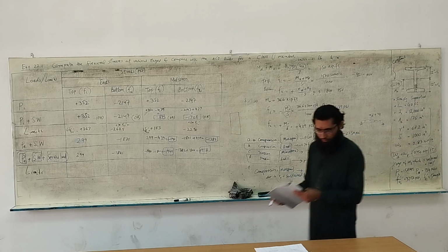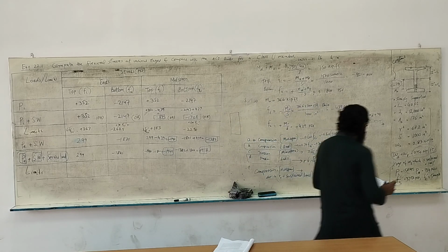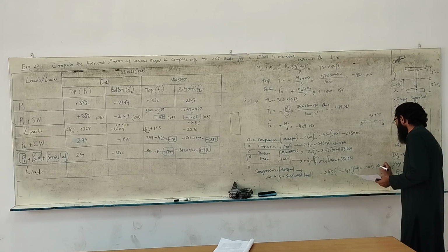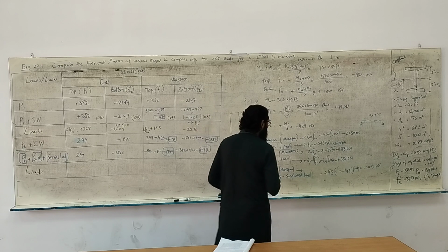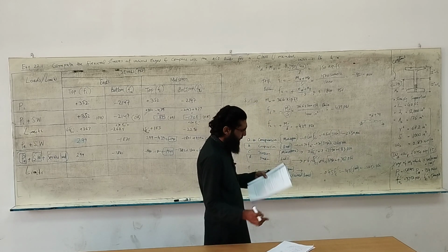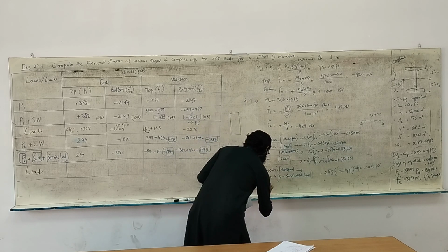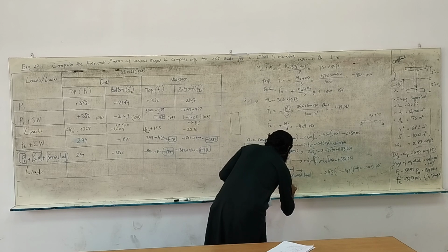So what is this answer? Minus 2250 psi. Okay, just for your knowledge, this F part is also a limit on compression, and it says extreme fiber stress in compression due to PE plus total service load. Again, it is for the midspan part.